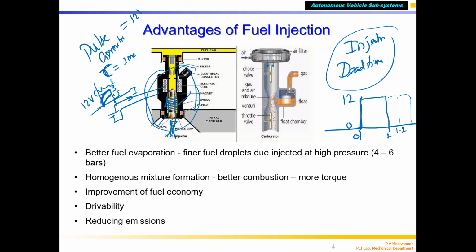You connect the injector to the fuel pump and all those things. But please make sure you don't put your finger near the injector outlet. The fuel pressure here is 5 bar, and the nozzle is spraying at 5 bar pressure. If you put a finger near that, the petrol can penetrate your skin and go into the bloodstream. But this is very low. Don't do this with a diesel injector. In a diesel injector, the fuel is pressurized to 1000 bar in a CRDI engine.